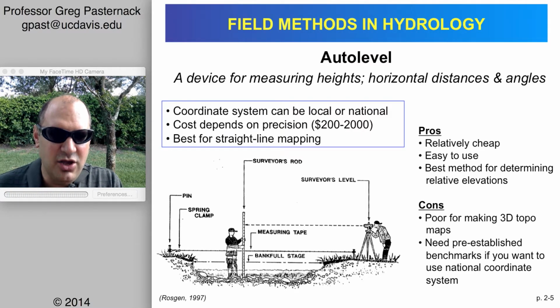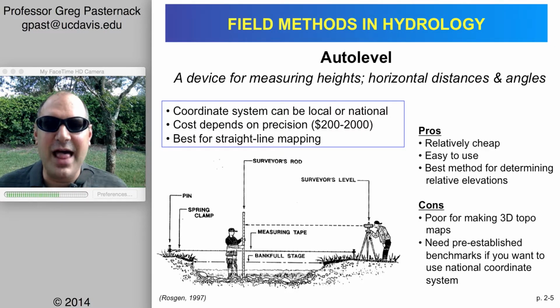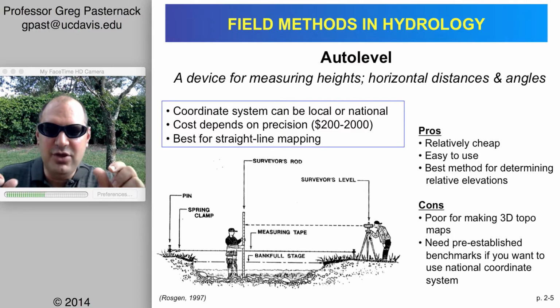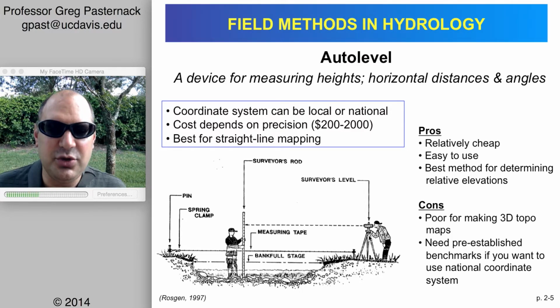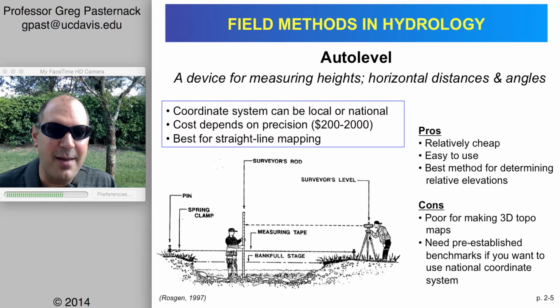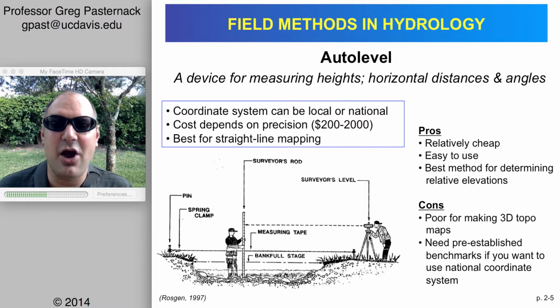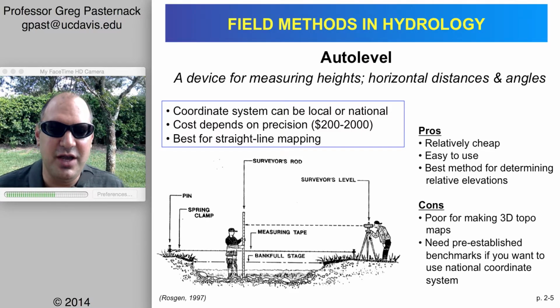Then you have, at the top of a surveyor's tripod, a flat plane, a flat metal surface, and we usually use these little wheels called screw jacks, and we can use those with a little air bubble in water that's built into the tripod or built into a base unit, something called a tribrach, and that's part of an auto level usually.